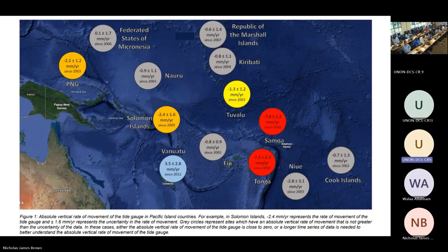Thank you, Nikki, for a good presentation. But we had the same problem in Tanzania, where we realized that even with the monument, the GPS, which was only a few meters from the structure itself, was deforming. Therefore, what I'm saying here is we don't only depend on the monument, which is a little far from the tide gauge, because the tide gauge monument itself may be deforming, and you may get erroneous results when you determine the tide. Thank you.